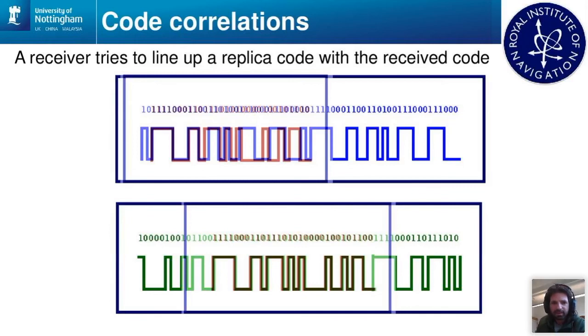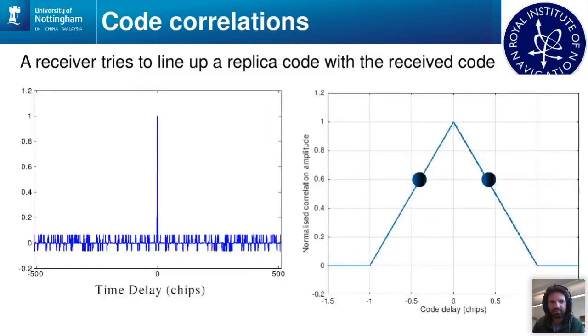Okay, so I'm going to have to hurry up a bit, but just to see what the effect of spoofing is, I wanted to show you what the receiver's doing, as we talked about, which is trying to line up these codes in the receiver. So if you imagine, it's lining up a code for each individual satellite, and when it does that, it gets what's called a correlation peak. And here you can see a large spike. When the codes are misaligned, it is anywhere but 0 on that graph, and when they're lined up, you get a big spike. If we zoom in, it looks a bit like a triangle there. And that's what the receiver tracks. It sets up a couple of points around it to track the received signal.